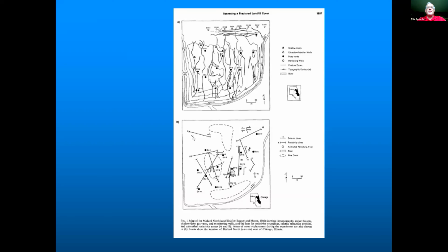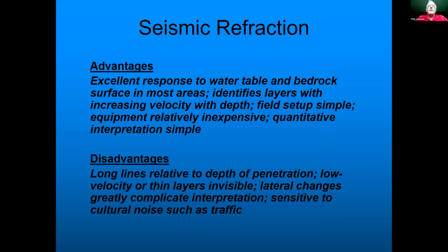It was very hot. So here are some of the lines we did. Seismic lines and resistivity lines are shown in the bottom diagram. The shorter lines are the seismic lines, the longer lines are resistivity lines. So these are resistivity soundings that we did to try to interpret the interior of the landfill using resistivity methods.